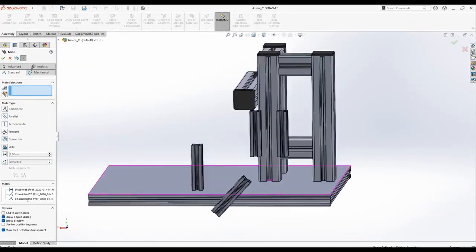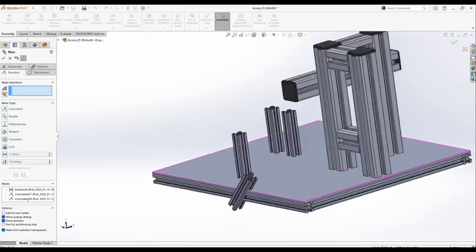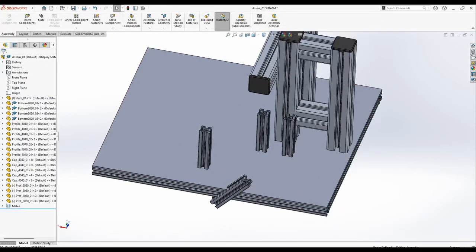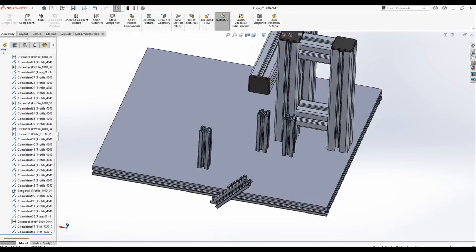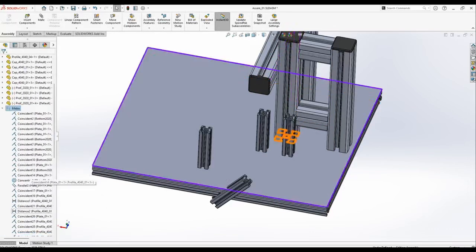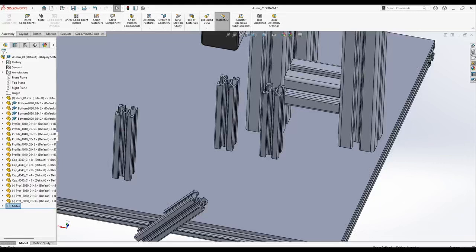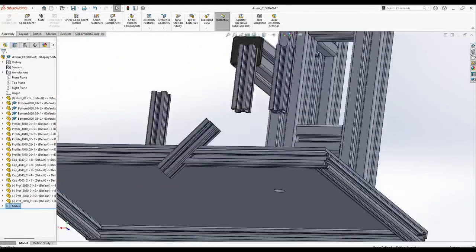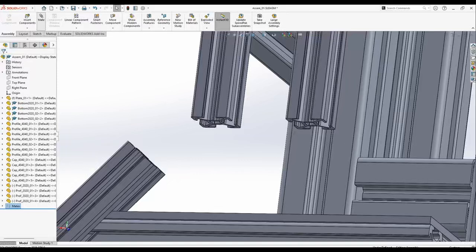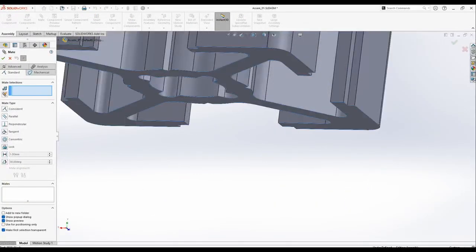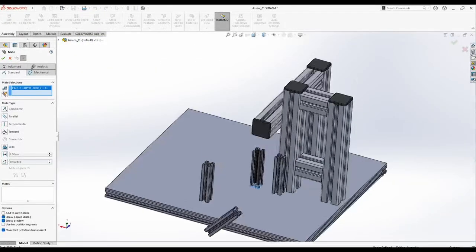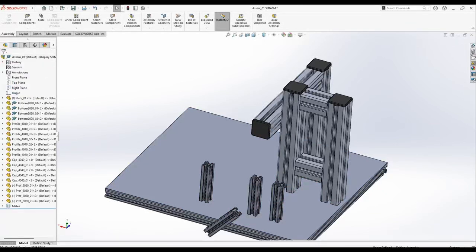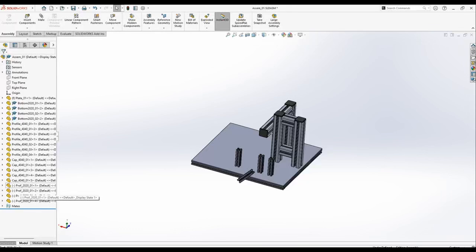And if we assign it, you see it's somewhere hanging on the top. If we assign it, you see the list of all mates is here, but still we need to place the vertical position. Checking again, choosing this, rotating with this, and now we position it well. Good.